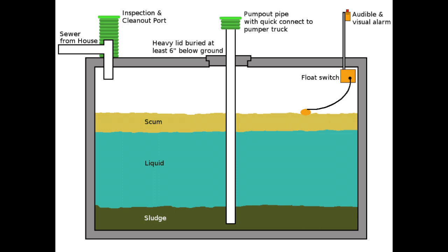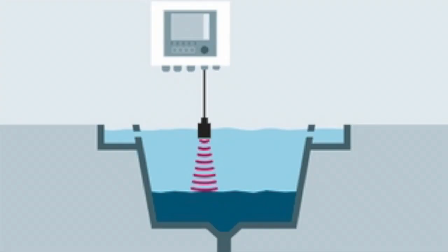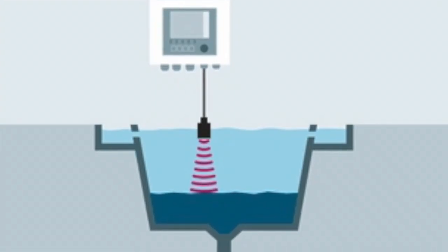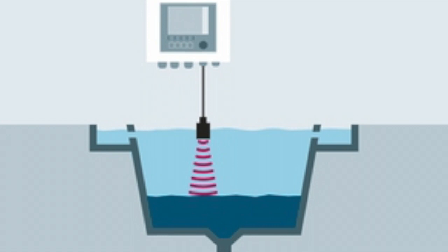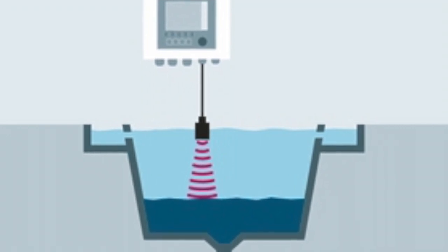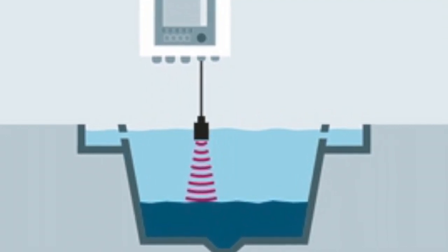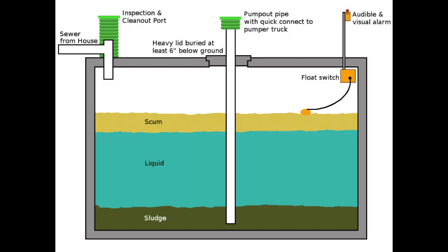The inlet and outlet of the sludge from the tank are the manipulated variables. An ultrasonic level transmitter is installed to perform continuous level measurement for uninterrupted monitoring of sludge volume. The disturbance is when the waste flow rate changes due to pump failure or blockage.